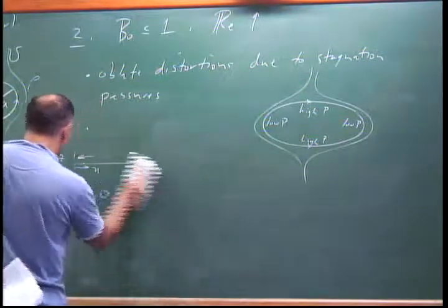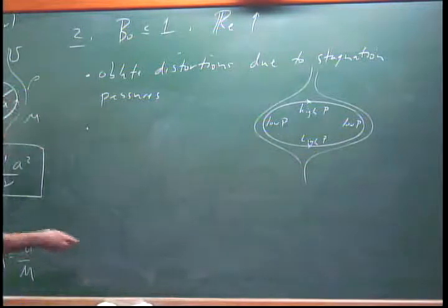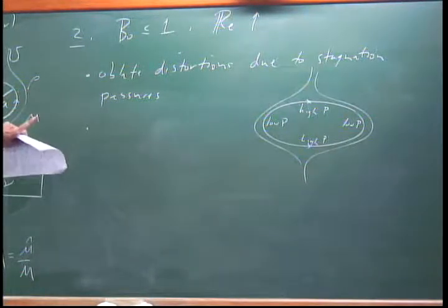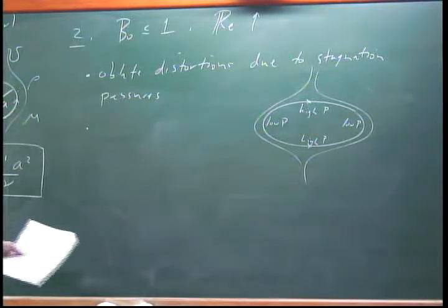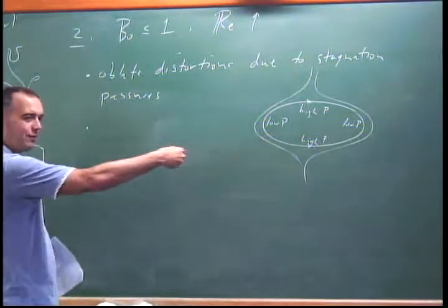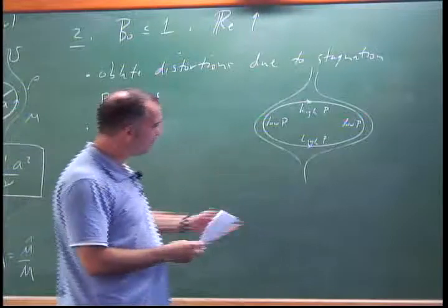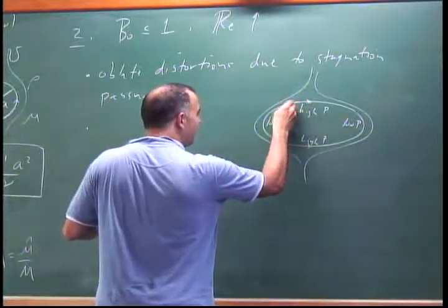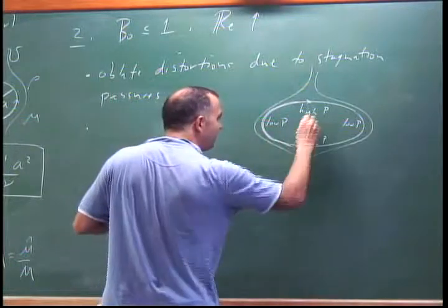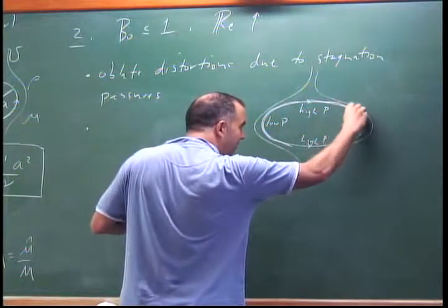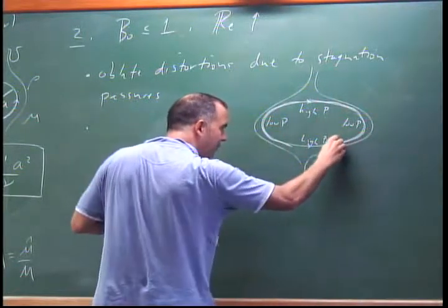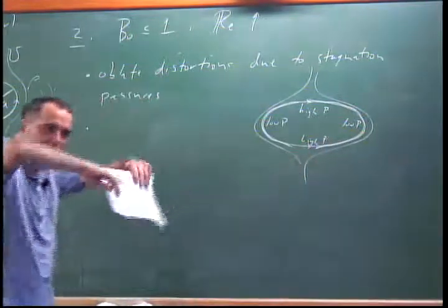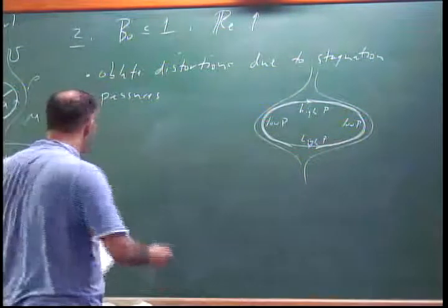Okay. So in any case, we've seen here that even at the surface of a bubble, you get the generation of vorticity, right? And it's not entirely clear that that should be the case, but that's what influences the subsequent development. As this thing rises, there's basically going to be a viscous boundary layer developing here, and this viscous boundary layer is a source of vorticity, right? So the flow around the bubble is generating vorticity.